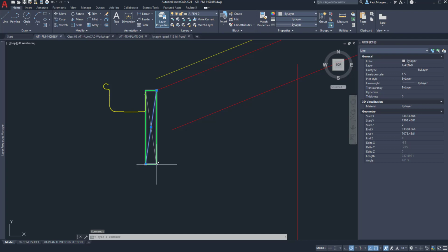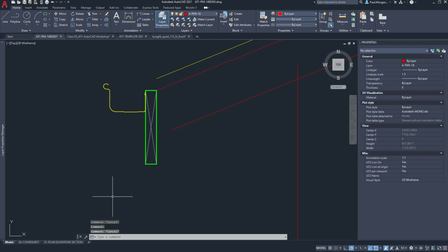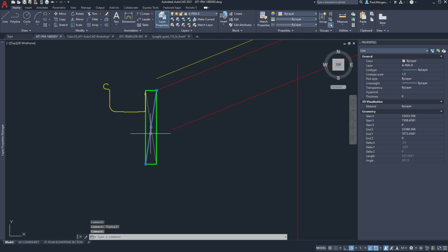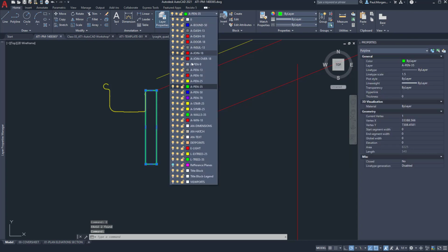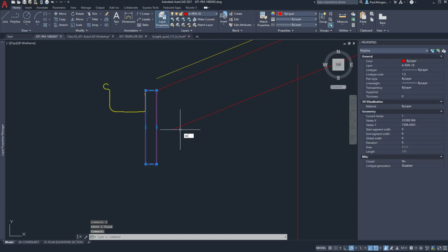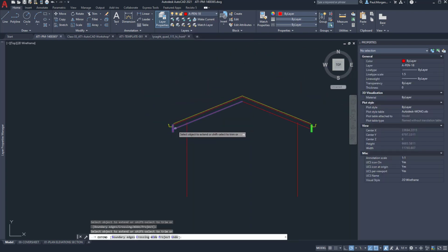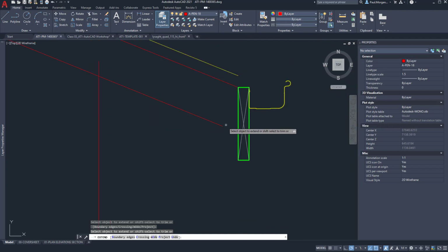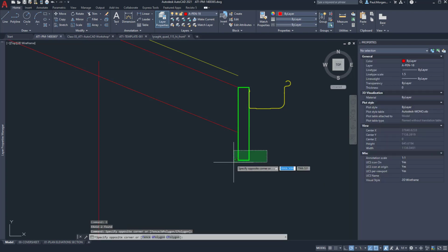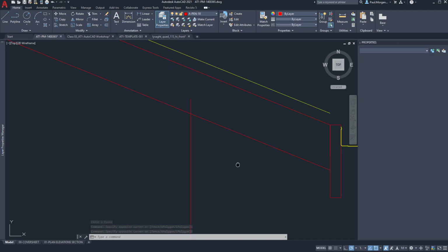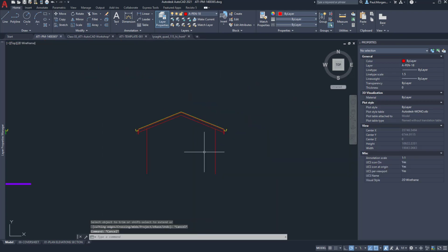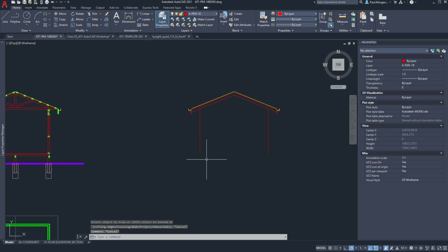These fascia boards here, they're not being cut in elevation anymore, so these don't have to be thick lines. So I'm going to get rid of the cross and I'm going to change this to a pen 18. Use the extend command to there. Do the same on the other side. Extend to there. Get rid of those lines. Change these to a pen 18. And trim. And that's basically one of our first elevations done.